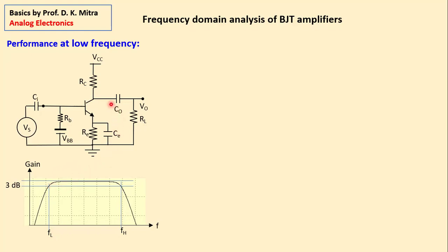So today we shall analyze this low frequency part. That means what makes this drop at this low frequency and how we can control this frequency. Suppose you are using this amplifier for music where very low frequency, that means the bass voices are also important. Say you want to use it right from 100 hertz, let us say. Say you want lower cutoff to be 100 hertz. Then what should we do? That's what we are going to analyze today.